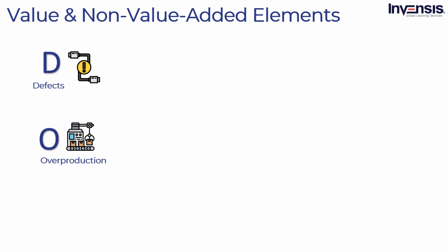The next one is overproduction. Overproduction means making something, like products, earlier or faster than needed or manufacturing more products than what is required. Some of them would be raw materials that are not required, work in progress, or finished goods without having adequate demand in the market. The best way to get rid of this waste would be by reducing large batches, building trusted supplier relationships, using value stream mapping, process mapping, and other good analytical tools.